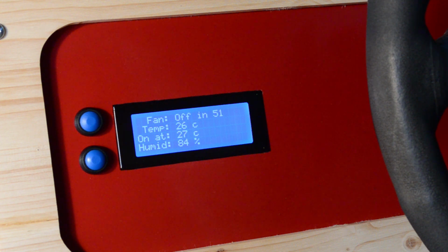And then it will go off. So as I said, I'm powering with 12 volts, and I've got a little power regulator to bring the 12 volts down to 5 volts that you'll see in the parts, so that I can power the Arduino. And as you'll see in a minute, what I've got is a signal line going down to my solid state relay to control the AC fan, because the fan is a 230 volt AC fan, right? So I'm controlling it with a solid state relay.